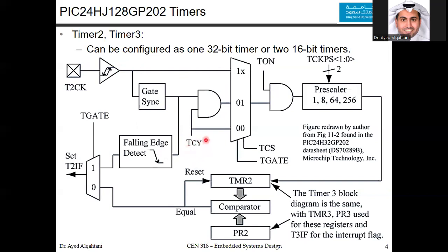So if you choose the internal, which is actually the obvious and the cheaper choice, then you need to adjust the multiplexer based on this choice. So you will take the selector's values here to be 0 and 0. So you'll get this value over here.